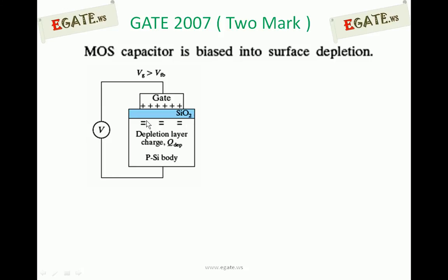Now the electrons are coming towards the channel region. These electrons recombine with the holes present in the channel first, so that hole-electron recombinations take place. That gives negative ions, so this negative sign implies these are ions. Negative ions are going to be created in the region. Negative ions are immobile, so they stay like that only. There are no mobile charge carriers present, so that is treated as the depletion region. So now the depletion region is formed for a small positive voltage.